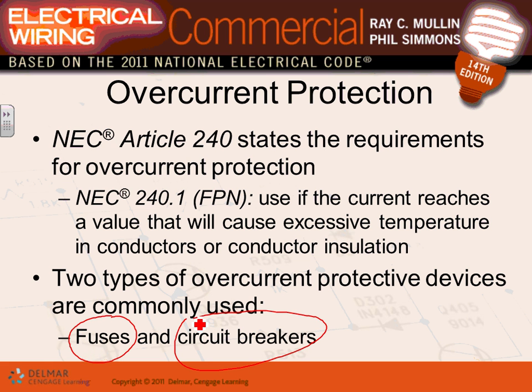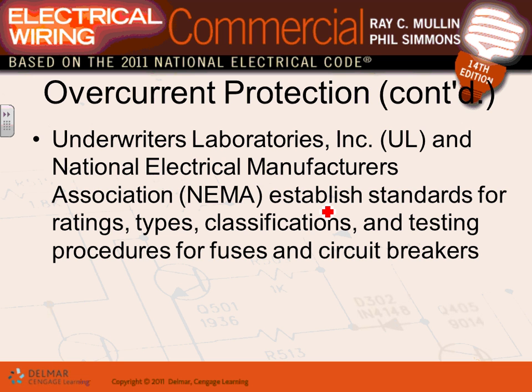The whole idea, guys, of having a circuit breaker or a fuse is to protect the conductor from excessive temperature because of short circuit or overload. If you don't care about your conductor smoking inside the pipes, if you have a ground fault or a short circuit, then a circuit breaker doesn't mean anything. Obviously, we do. So you have to install your overcurrent protection device, use a circuit breaker to protect these conductors based on their ampacity.